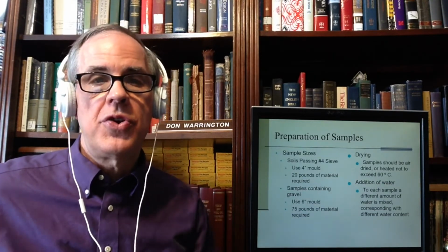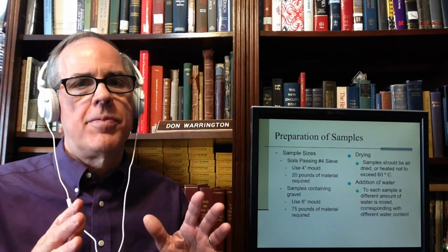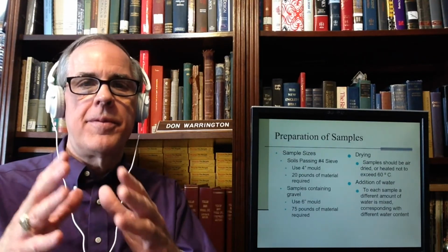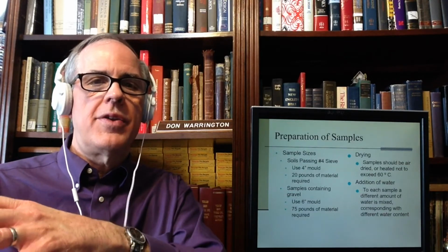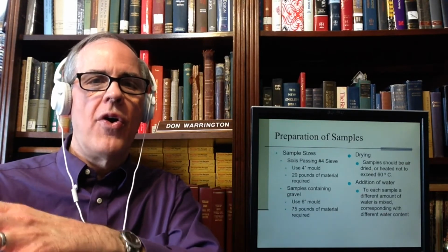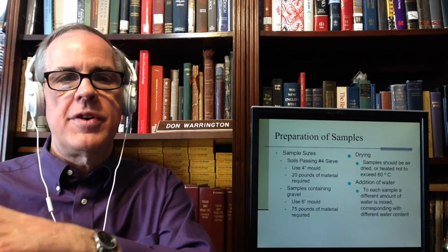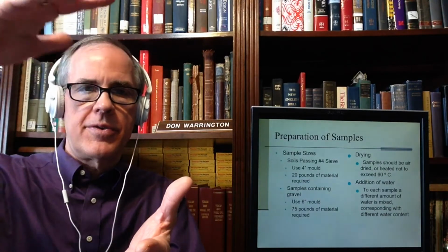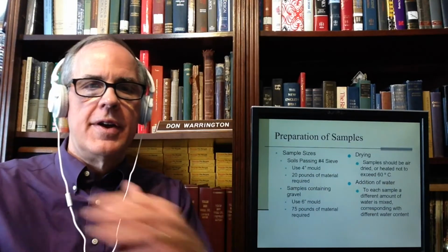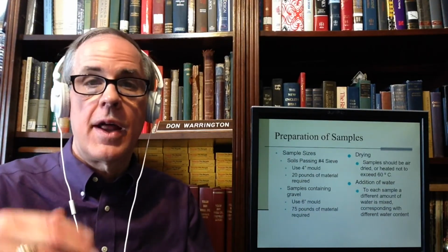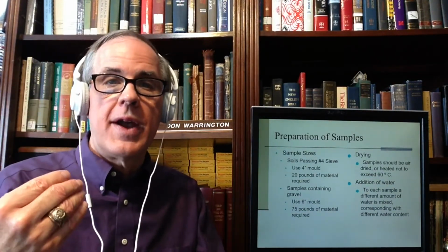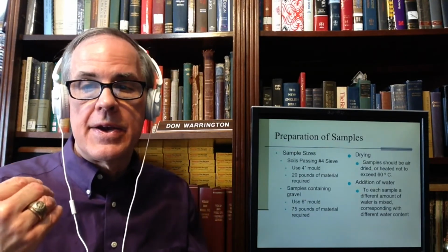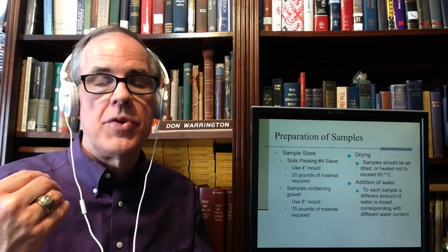What you have to do is kind of like the Atterberg limits in this respect. To do it by the book, you use a different sample for each compactive cycle, in other words, each set of 3 or 5 lifts and blows.